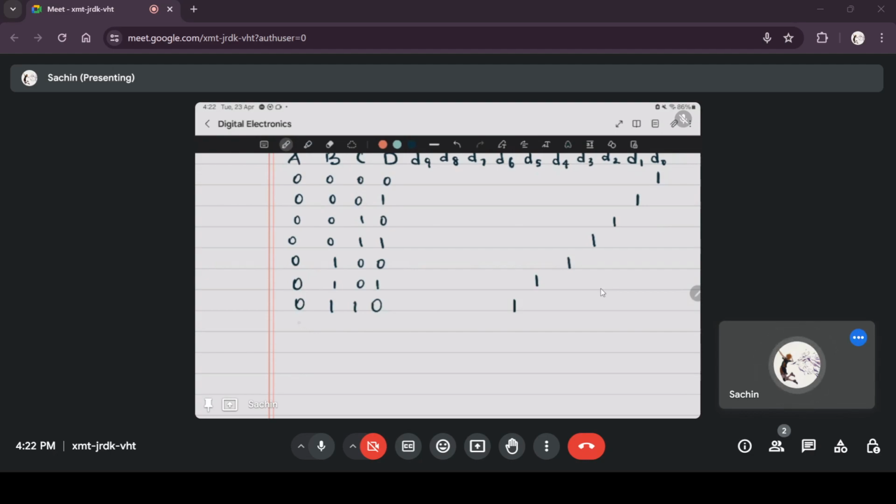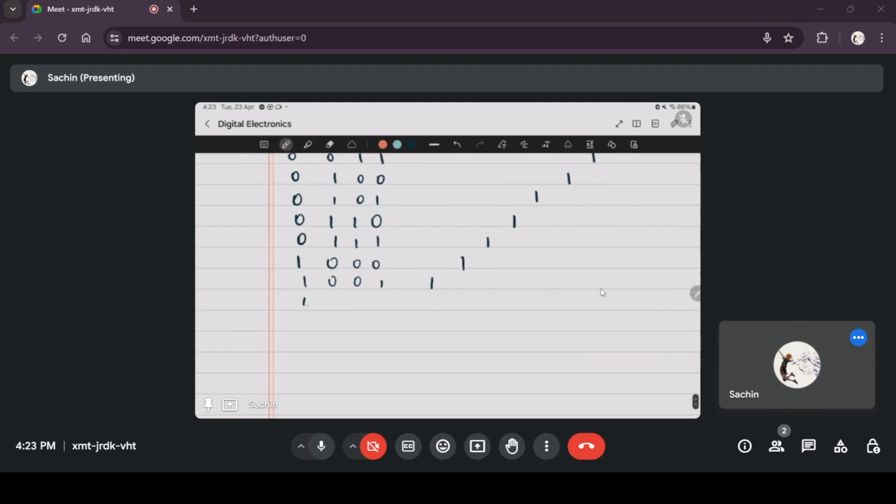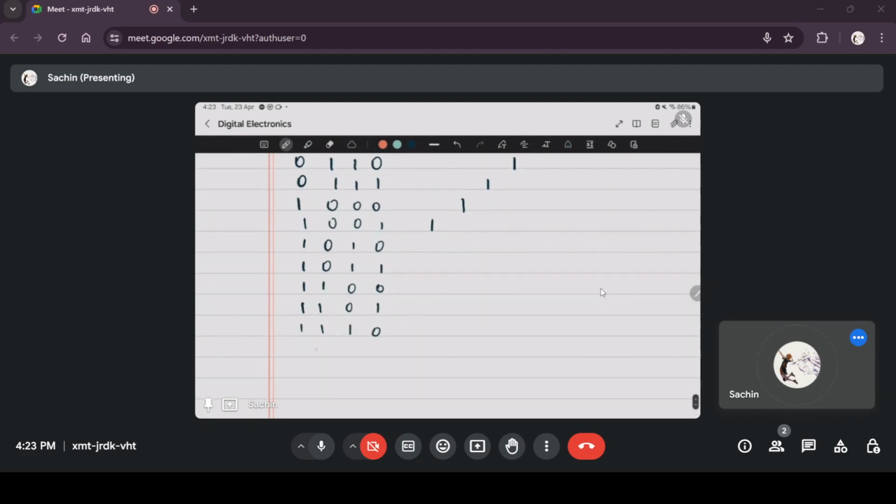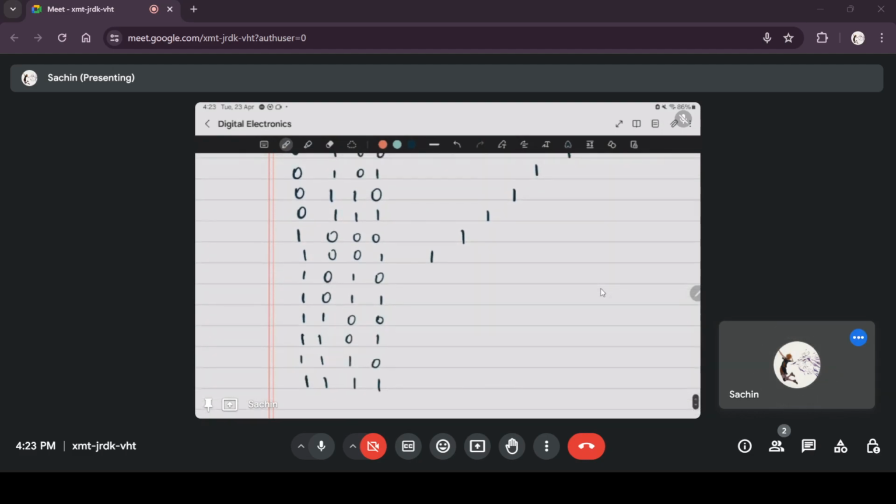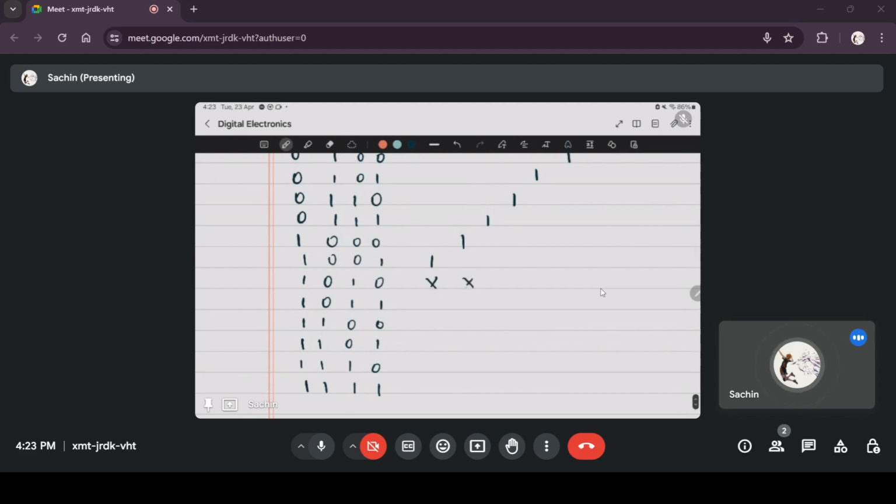BCD 6, you select D6. BCD 7, you select D7. BCD 8, you select D8. And BCD 9, you select D9. And for the rest of the combinations 10, 11, 12, 13, 14, and 15, these are all don't cares.